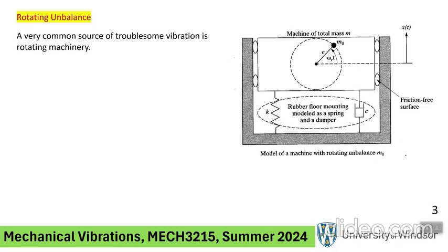That being the case, essentially we can treat it as a mass at a distance, which is the distance between the mass center and the axis of rotation, denoted by little e, the eccentricity. So we can view this whole shebang as a mass of m naught rotating about this point, maybe connected with a massless rigid bar. Okay, so this is a simplified version.